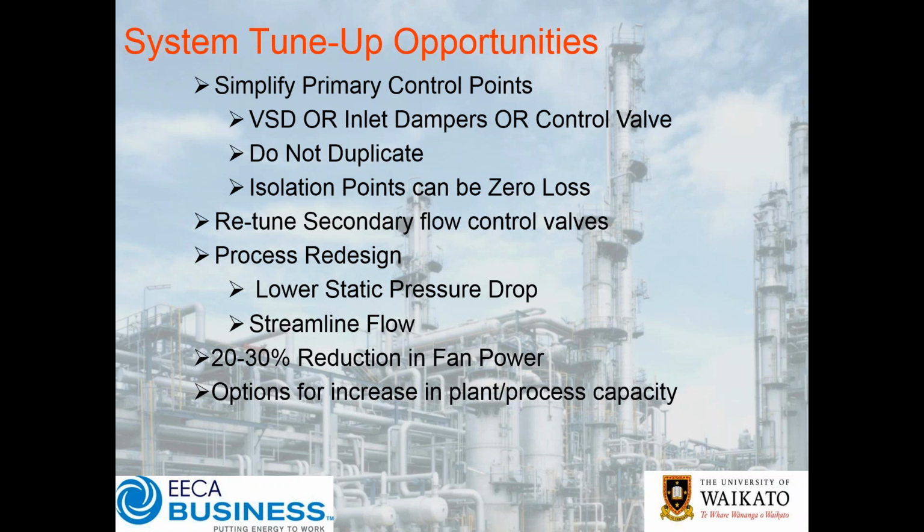Just to reiterate, if you've got secondary flow control valves, butterfly valves, dampers and the like, trying to retune them, or if possible eliminating them, can be a huge gain to your system. Understand that your system or your reaction vessel, your fluidized bed or whatever it is that has these multiple inlets, typically is going to have a reasonable pressure drop across it, and in most cases that pressure drop is more than sufficient to ensure adequate uniform flow without having additional dampers, which often you'll get operators playing with and tweaking with and doing more harm than good.